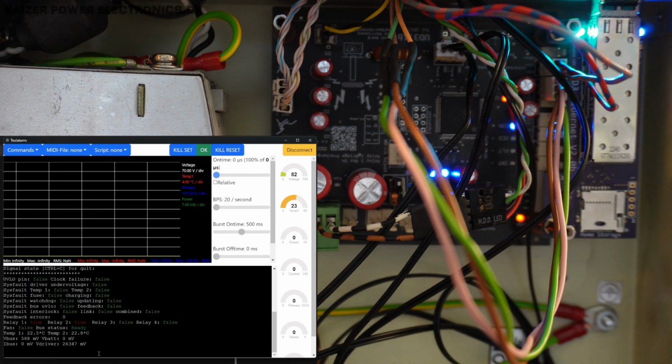Using the signals command, I could see that the VBAD was getting an input voltage and not our VBus. So apparently the connector on the UD3.1 PCB is different between the VBus input and the battery input on the connectors compared to the UD3 PCB.